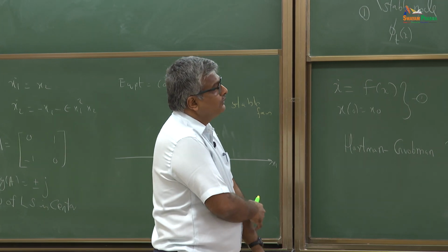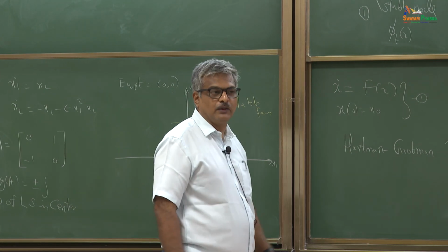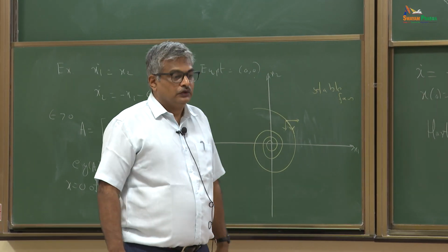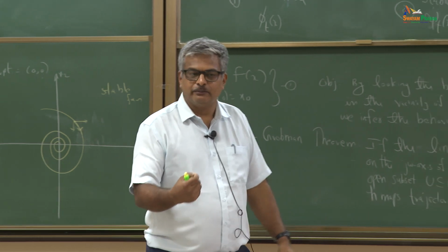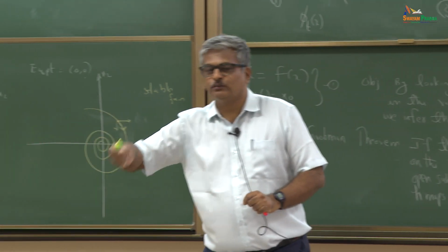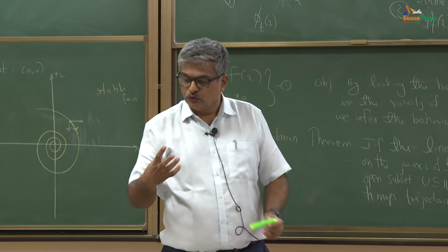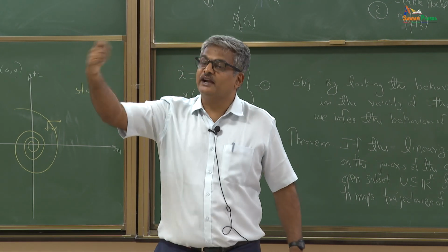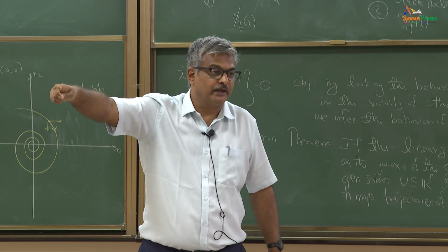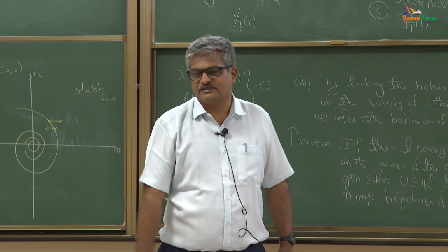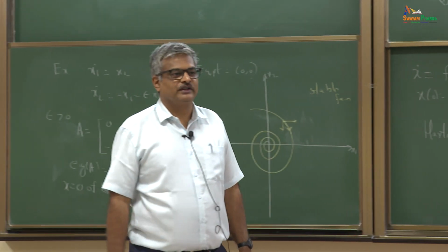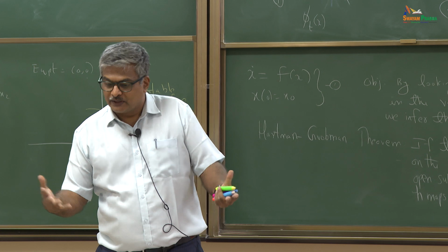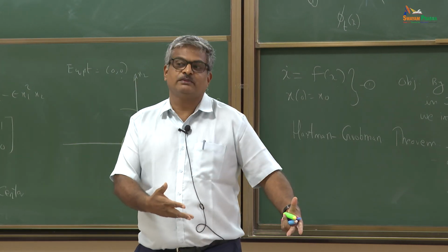Why do we need the W x s? There is something beyond this explanation. You have a nonlinear system, you have an equilibrium point, and you have some other equilibrium points also. So you want to find the domain of your equilibrium point of interest, such that if you start from any initial condition in that domain, you will reach the equilibrium point of your interest and not escape to some other equilibrium point. That is very important, because then you know how much perturbation it can take, and where I should initialize my system.